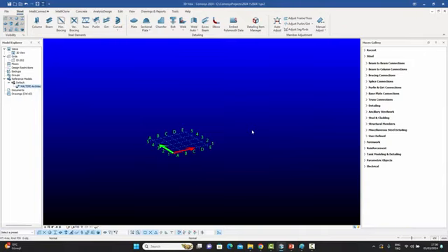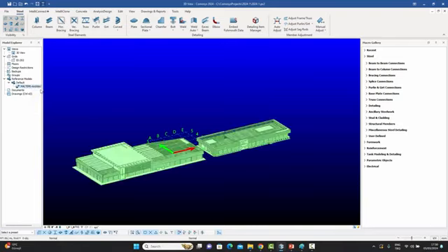Had it been a normal IFC import, you would need to continuously manage it by selection and all that. But in this case, you can just right click again and say show, and the entire reference model is shown on the screen once more. So this is the basic advantage we have once the entire reference model is automatically saved under a group. We can show it, hide it, update it if the source file changes and bring it back in. We can delete it, remove it from our list of models, and re-import it later.